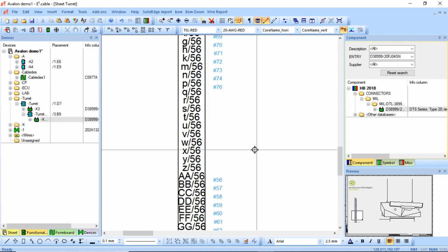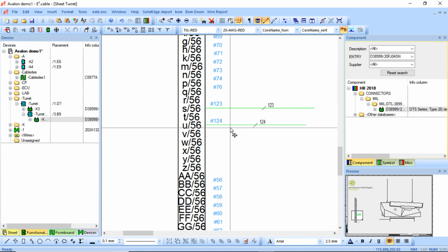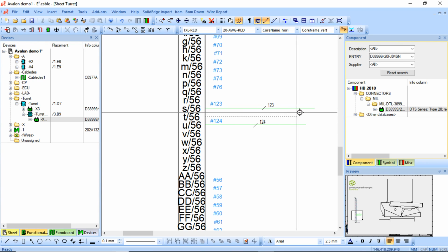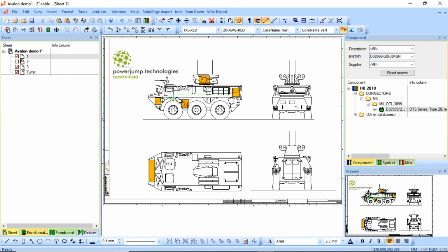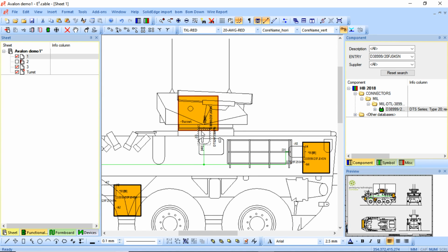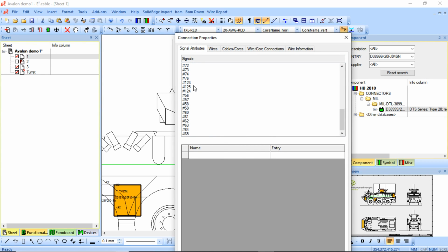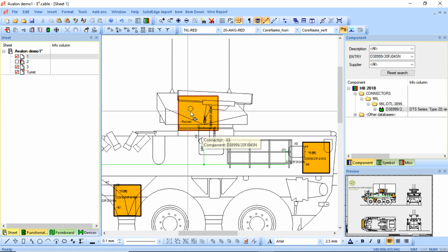So if I was to connect new cables within that, each time I create something new, it will automatically place a new signal, like so. So the 1, 2, 3, 1, 2, 4, 1, 2, 5, if I go back to my main overview in here, so in this particular connector, for example, it will now have those 1, 2, 3, 1, 2, 4 and 1, 2, 5 symbols. So any logic I have within this particular hierarchy, I can have a subset of other systems and circuits and everything else. The signal logic will transfer from that to that.